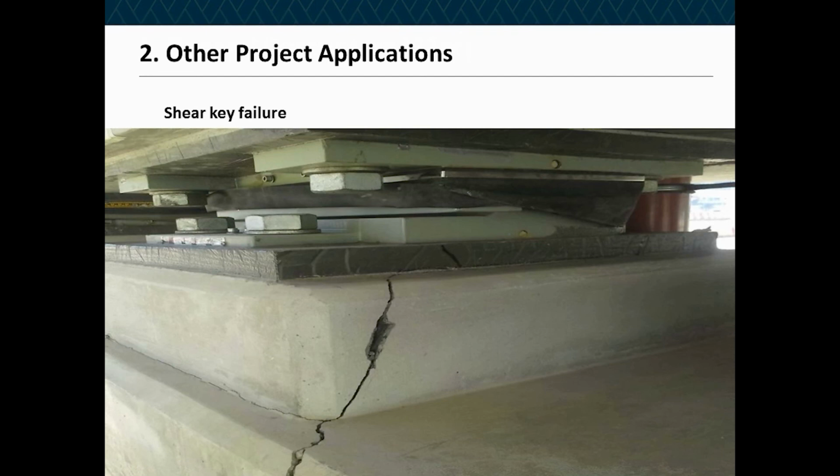So they had a rail on top that was free to move, and they had two sets of bearings underneath that were not. And basically on an uncharacteristically cold and wet Dubai night in February a couple of years ago, the two bits of track either side of this pier decided they were going to pull the bridge apart, and they pulled the shear key off of its plinth, or out of its plinth, and this crack actually extends down into the middle of the pier.